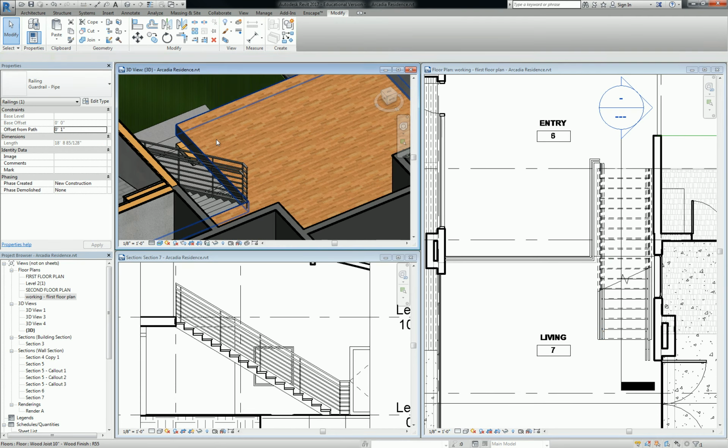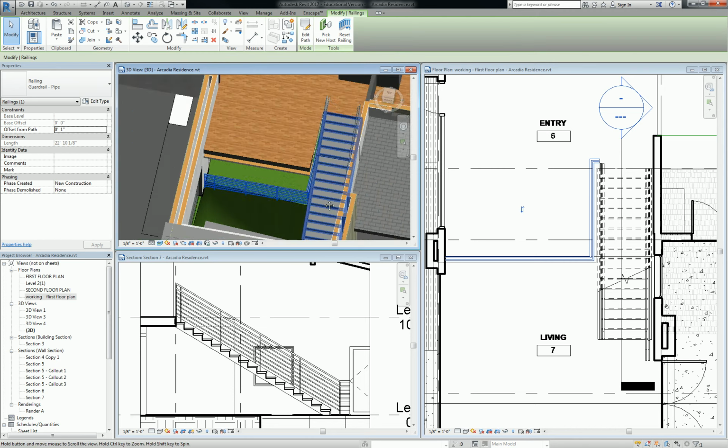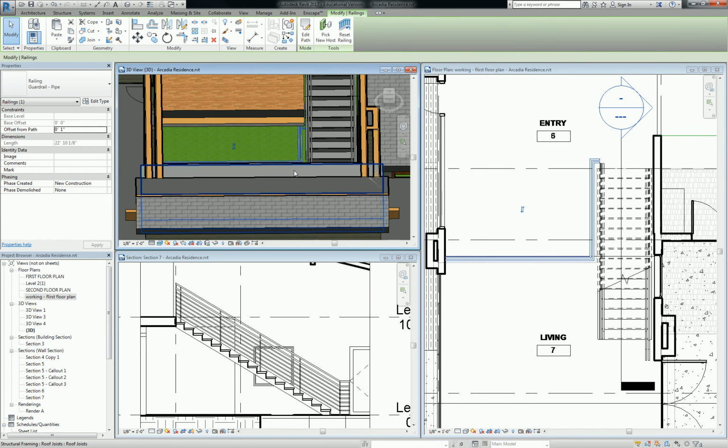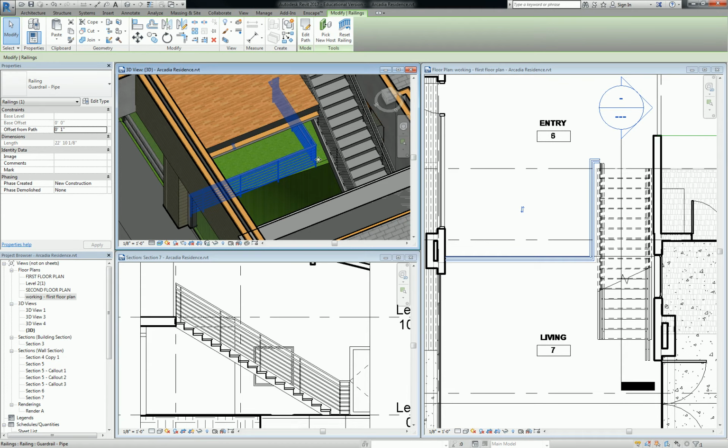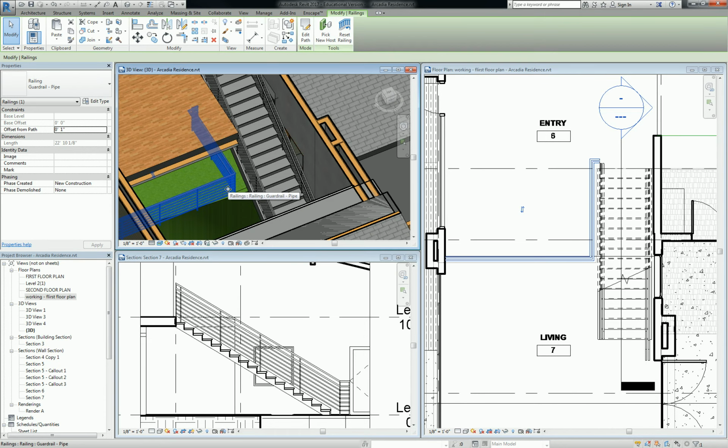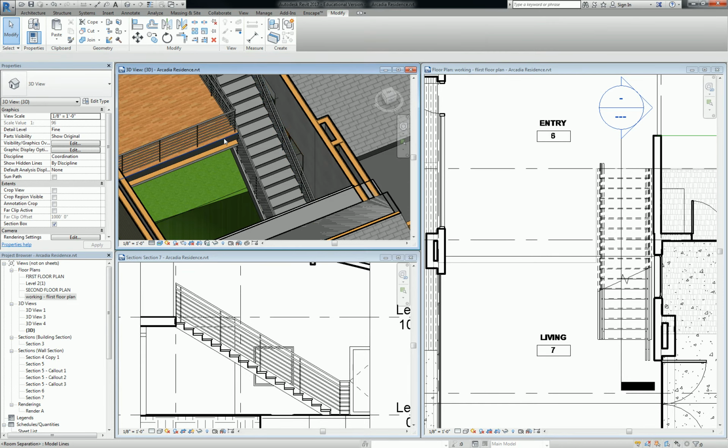So now I've got, whoop, look at that. So it broke, and this is your first little understanding into Revit railings. So this particular element needs a new host. So we drew or started the stair on level 1, and so the railings were associated with the stair. And when I disassociated this railing with the stair by it being located off of the stair, it still went with level 1 as its base. So we can pick a new host and select the floor and it'll jump up.